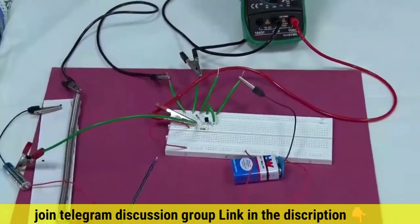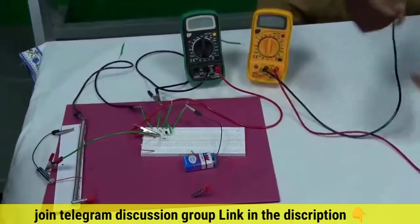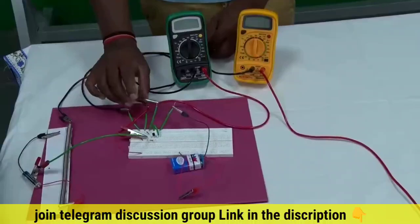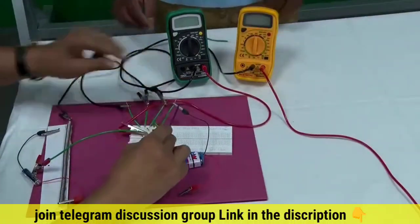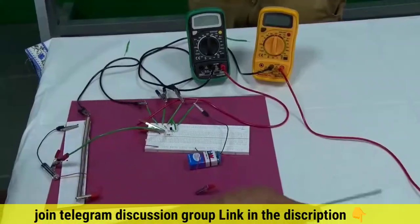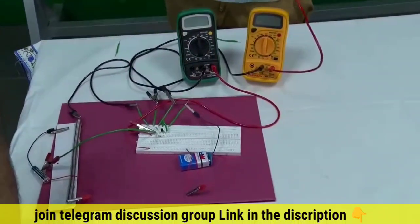Then the output side. In the output side, once again the black terminal should be grounded, 0 potential. So, see how the circuit is implemented nicely. This is also at the same potential. All those negative terminals, all those black leads, are joined together. Here they are all joined together. Okay. And the positive red terminal should be measuring VO, the collector. So, it has to be directly connected to the collector.